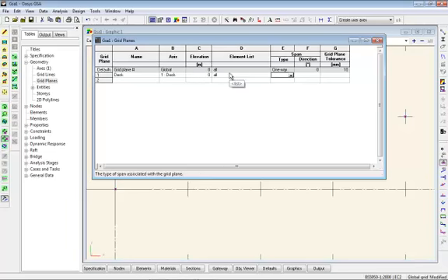If you're doing a steel bridge with plan bracing, you can choose to exclude those from this, because this grid plane is going to be used for loading the bridge grillage that we're going to make. As part of the loading, we need to specify the span direction. If you have a straight bridge, you might get away with a one-way spanning bridge. This is going to be curving a bit, so we're going to have a two-way bridge, two-way spanning on each panel. Two-way and multi-way will give you pretty much the same results, except that two-way is quicker on the analysis.